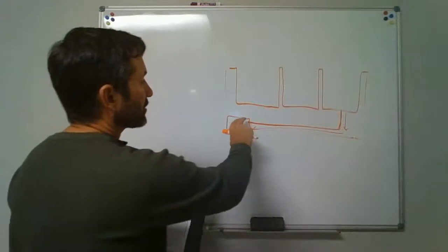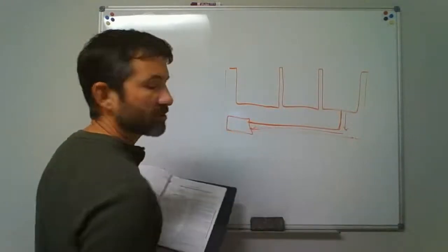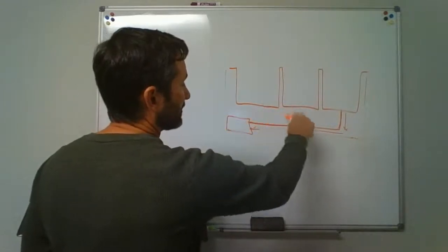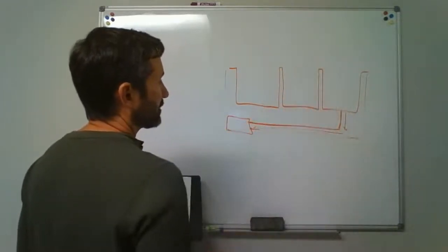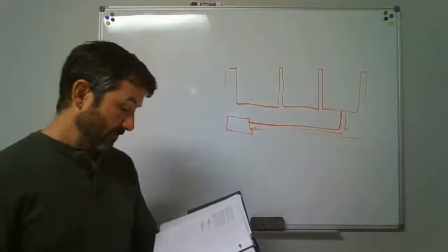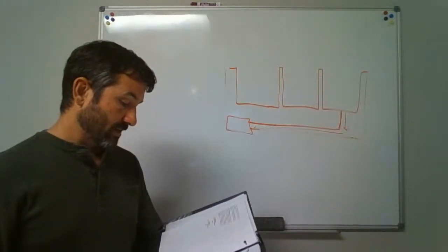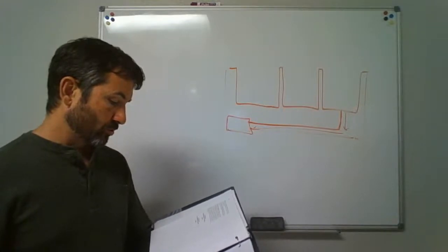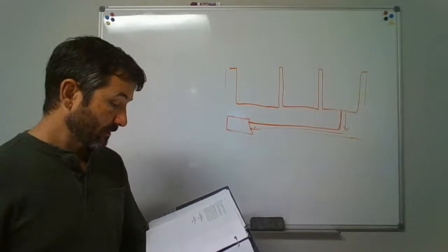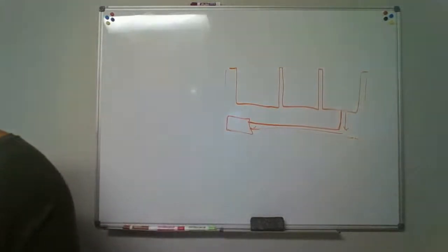Now, what you can do is just say, oh boy, we're pushing it right at 60, or we're a little over. We'll just slide that thing over, plumb these things down into where your most upstream is, and you can normally make that work. Okay. The connection of a laundry tray, complying with section 802.3.3. Okay. There's an exception there.